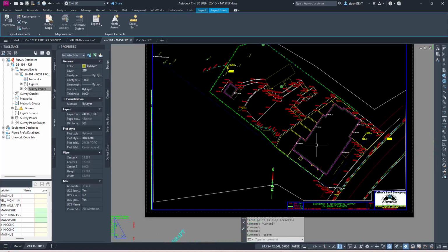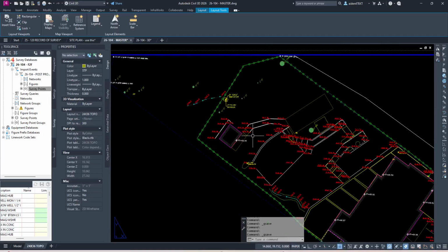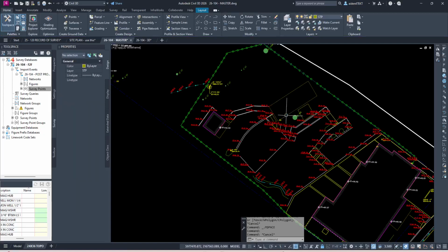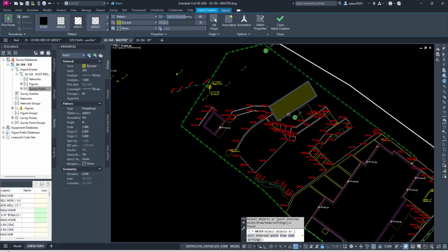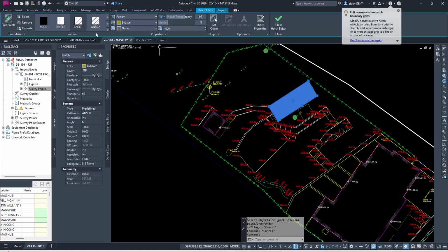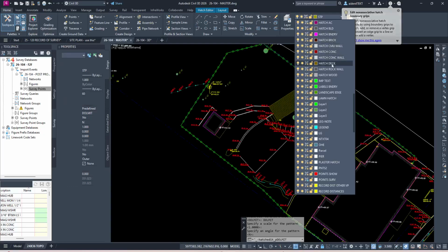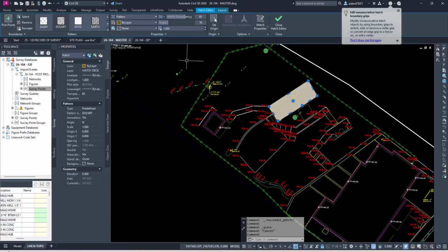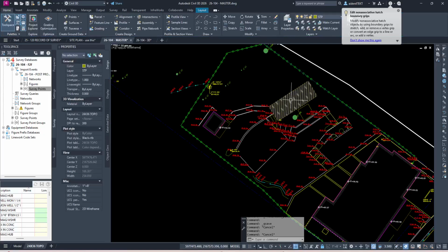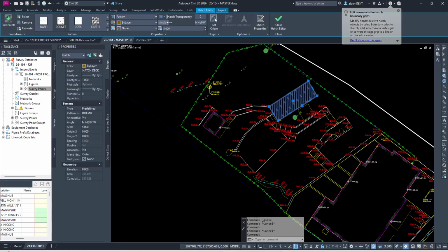So that's pretty much the 2D stuff, cleaning it up, and then sometimes we do hatching. So we'll hatch the deck, and you put ABC dolomite. There you go, dolomite, and then it's on the specific layer it's supposed to be. So match the deck, and you have to scale it just right, 5 or something, with transparency 0, and whatever way the decks are going, you can move it.